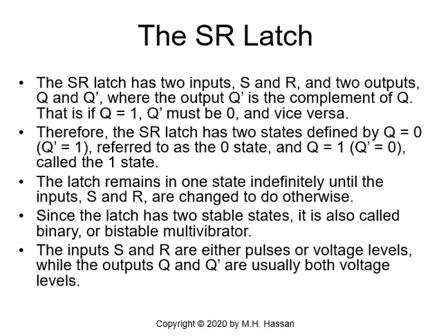Now, if the latch is at the 0 state without any excitation, the latch will stay at the 0 state indefinitely until the inputs are changed. The same thing with the 1 state, so both are stable states. So the latch remains in one stable state indefinitely until the inputs S and R are changed to do otherwise. Since the latch has 2 stable states, it's called a binary or bistable multivibrator.